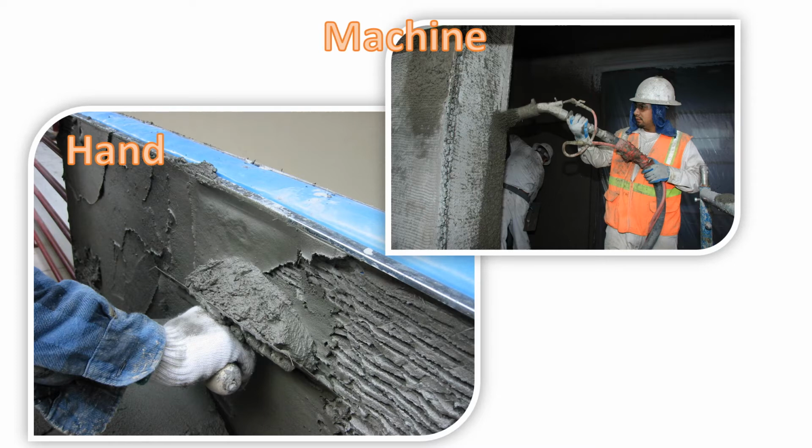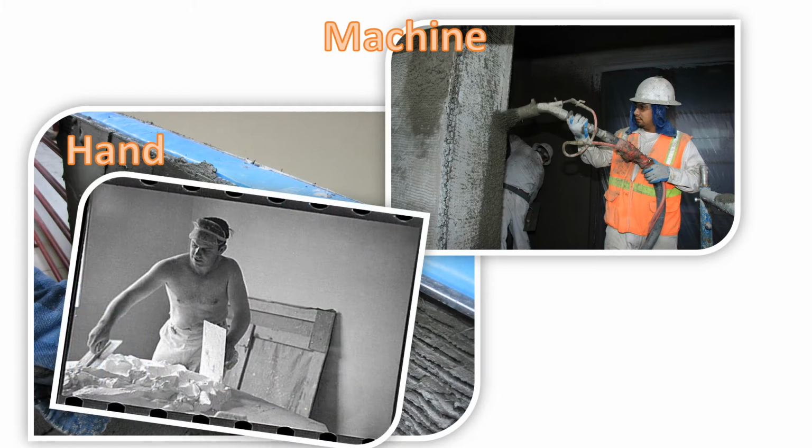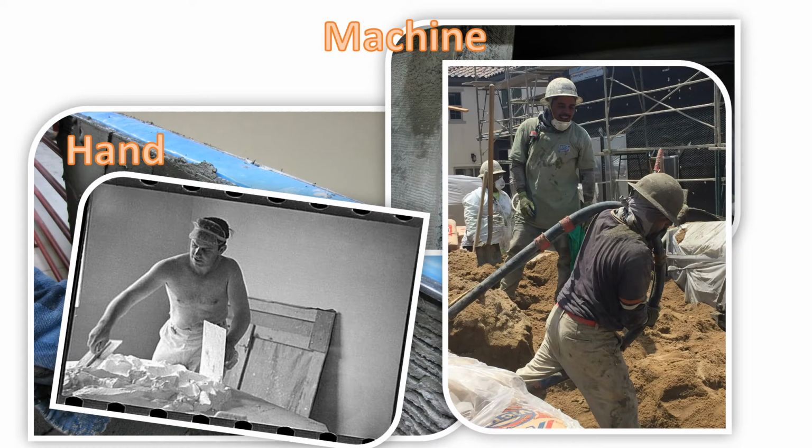Another factor in the consistency of the mix is the method of application. Hand tool application generally requires the use of a mortar or mud board. This mix may be preferred to be a little stiffer or have less water. The machine or plaster pump generally requires a looser or more wet mix. This is because the material must be able to move and pass through the hose without blockage. The hose can also absorb some of the mix water as it travels through the hose.